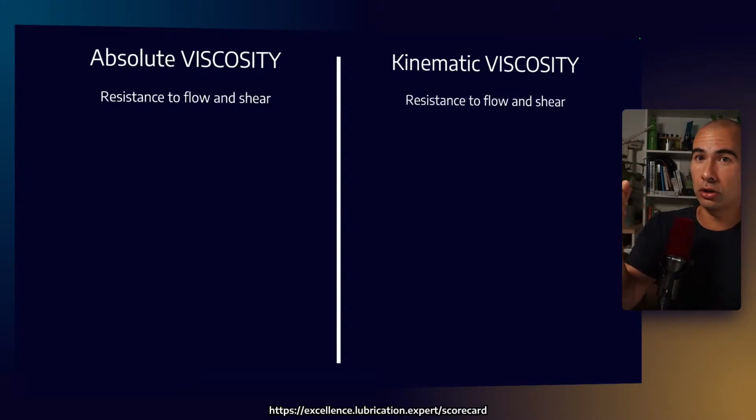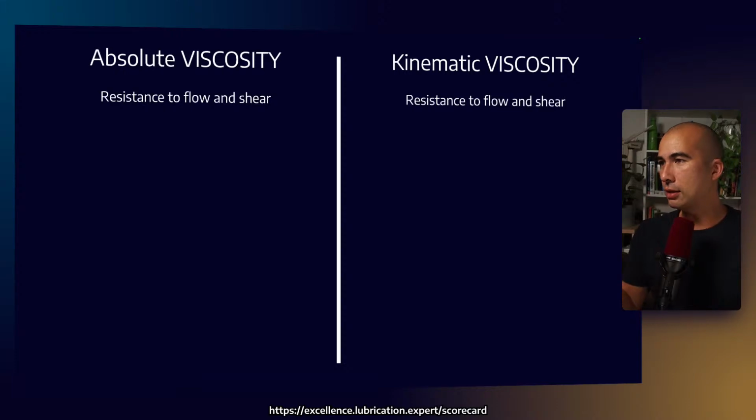The answers are viscosity, viscosity, and viscosity, right? Now, I'm not just saying that to be pretentious. It's the bulk viscosity of the oil, viscosity's relationship with temperature, and viscosity's relationship with pressure that are the three most important properties.